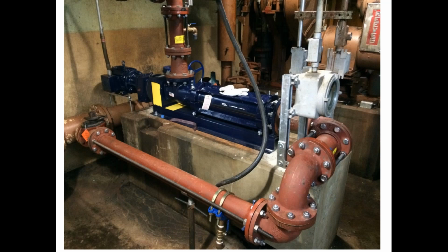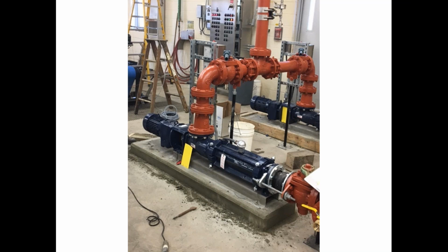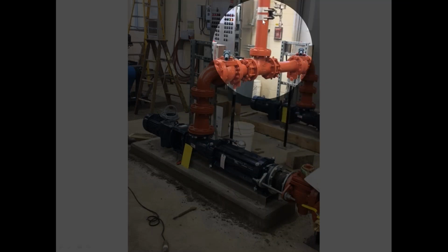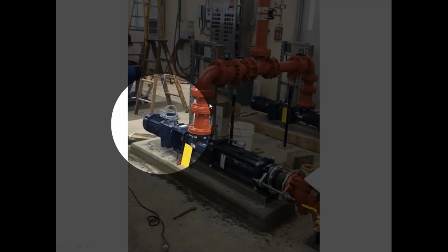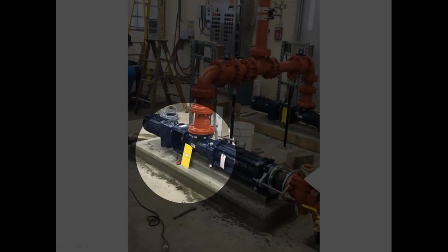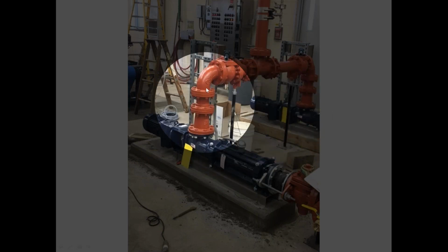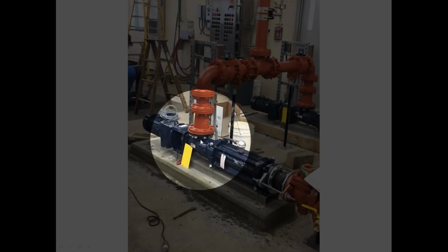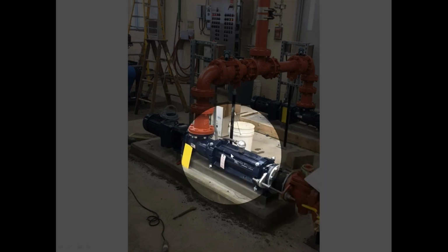Other applications for these pumps. This right here is in Block Island, Rhode Island. As you can see, there's 2 progressive cavity pumps with a common header. The drives are back here. These yellow plates are covering up the mechanical seal. Typically, we would have suction coming in this way and discharging out that way. This is your split state or wet end. And this is a thermal probe that is sensing for temperature inside of this pump, all provided by Seepex.